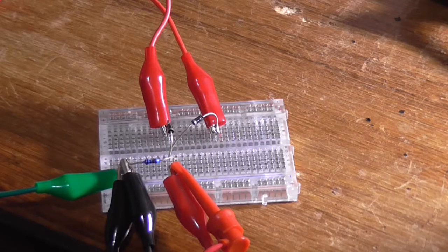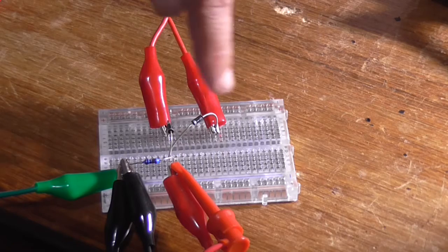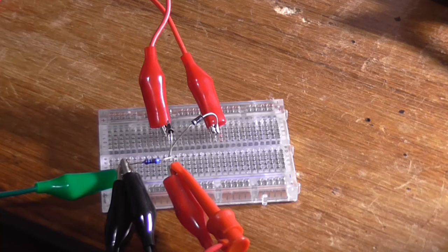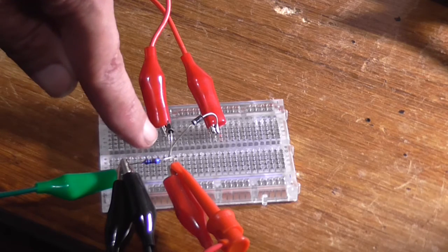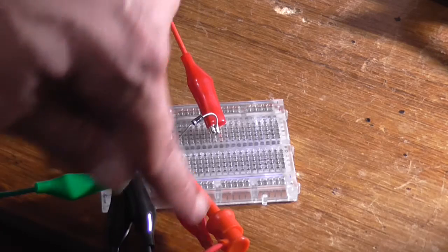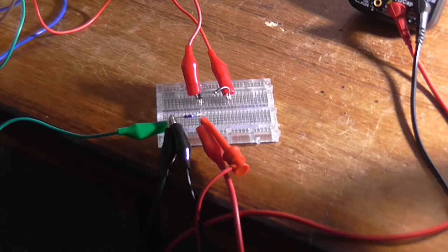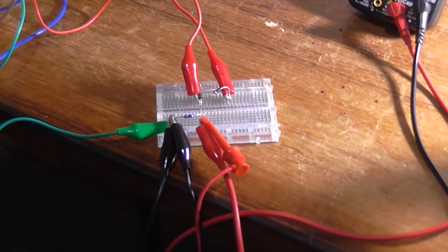So on the positive going half cycle of the AC waveform, this diode is going to conduct and current is going to flow through that direction. And on the negative going half cycle, this diode will conduct conversely, allowing current to flow through this direction and returning via the center tap. And that is basically how the full wave rectifier works. The advantage of this is that it can provide more current. The disadvantage is you need a center tap transformer, and it only produces half the voltage from said center tap transformer. However, this can be fixed by using the last form of rectification circuit, which we're going to look at now.